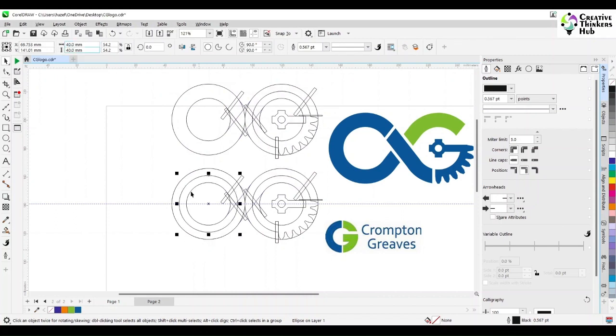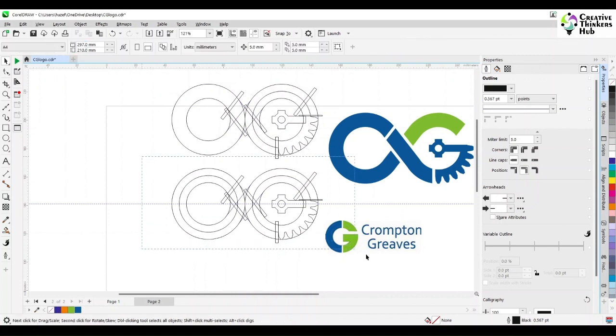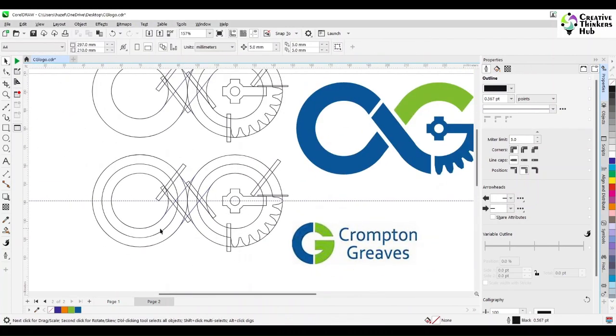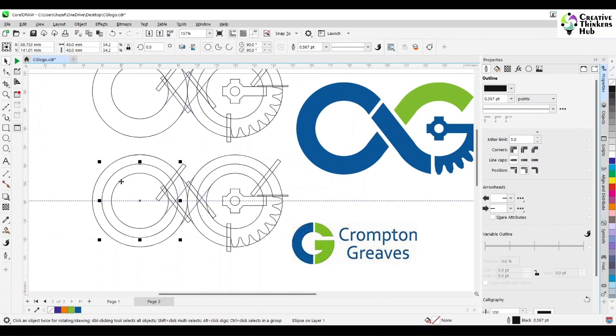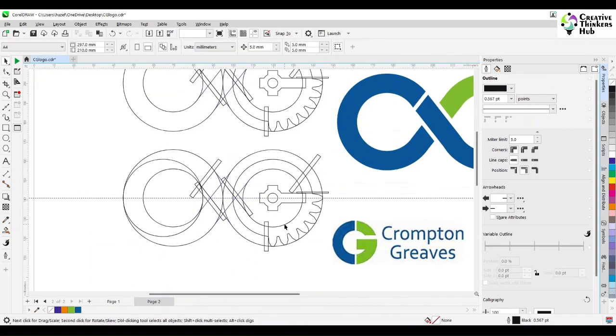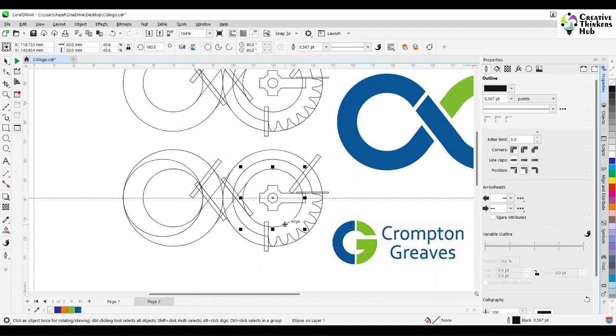For that we copy paste this and put it at 40 degree, 40 mm. Once that is done, we select both of them and click R, so this gets right aligned. And for this one, we copy paste this center circle and increase it to create that graphic element.